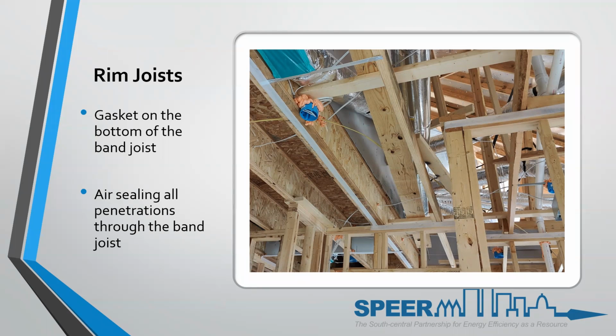Again, if it's left off during blower door, you will see this with an infrared camera. You will see air movement through this junction, because every time it doesn't have a staple or a nail or a screw, it's allowing a pathway for air. So make sure they're still at the bottom. It should be in the scope of work of either the insulators or the air sealers or whoever does poly seal.